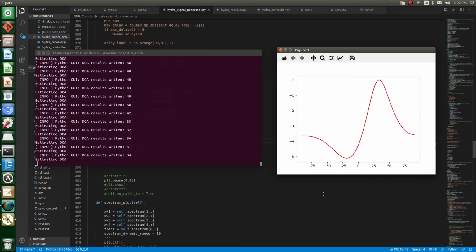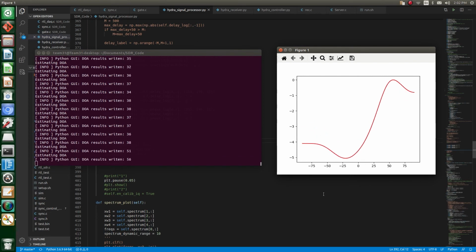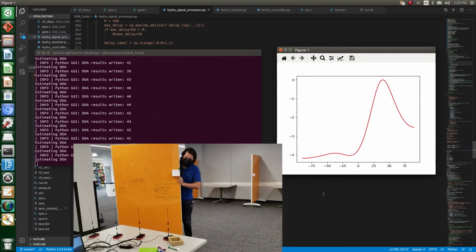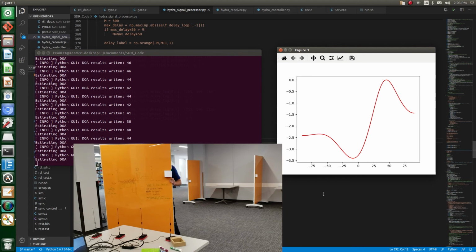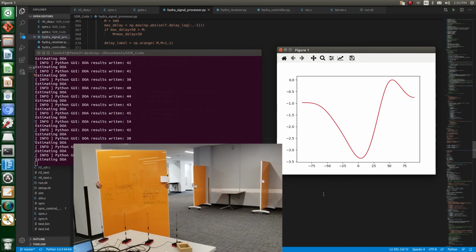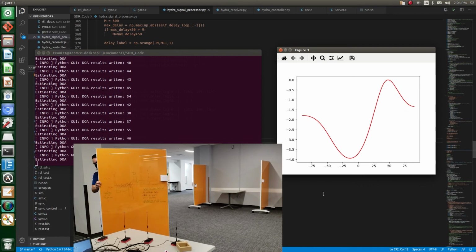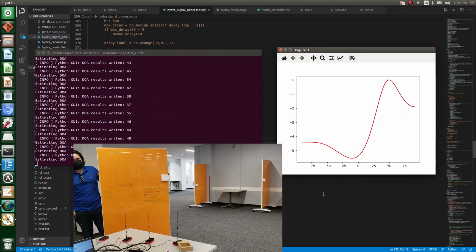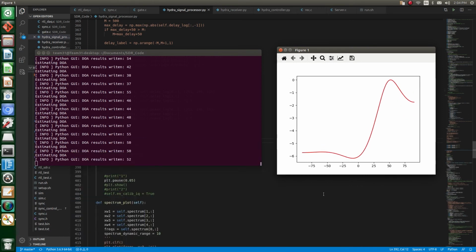In order to see if the direction of arrival could be manipulated indoors and detect other reflections, we decided to take a giant whiteboard and move it around the array. While the board is moved around the antenna elements, the plot changes and shows a distinct rise in the detection of an incoming signal around negative 55 degrees. This is approximately the angle at which the whiteboard rests with respect to the array when it is located to the left side of the array.